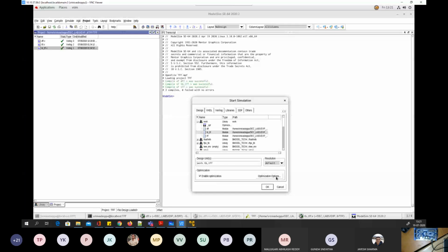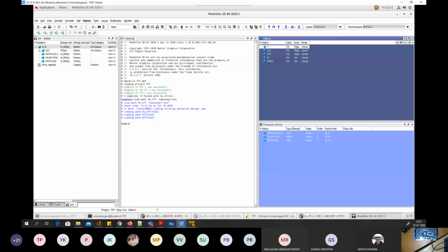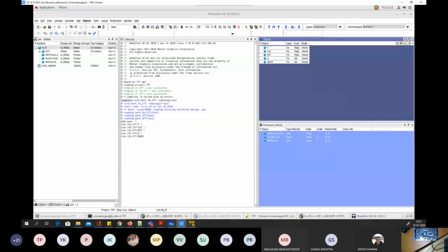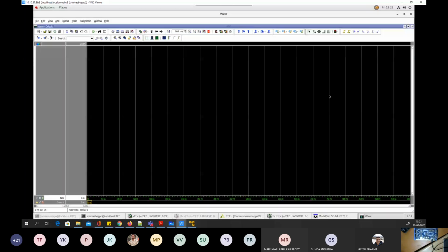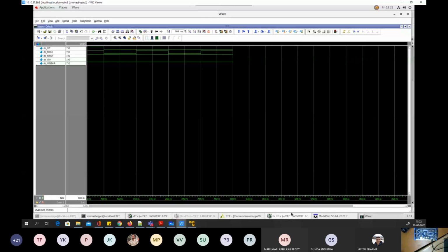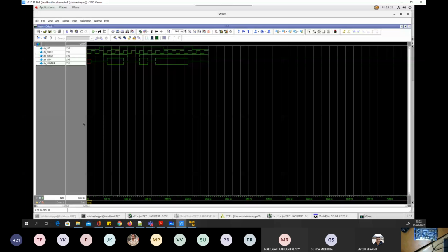So it will open something like this, and then what we need to do is just select all these signals and add it to wave, select signals. Okay, so maybe I'll undock it and then simulate, start simulation, sorry, now run simulation, run minus all. It will ask you to finish, say no. Okay, now you'll be able to see the waveforms. So maybe undock it. So now here you have similar waveforms, and again either use this approach or that approach and just validate the design. As I said, you need to convince yourself that okay, it's working correctly. Okay, so this you can do it.